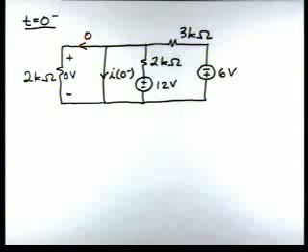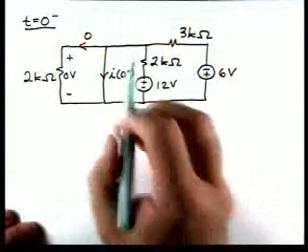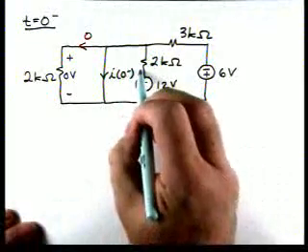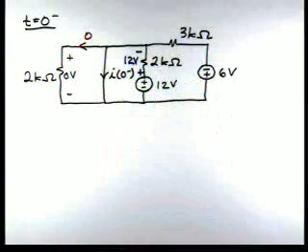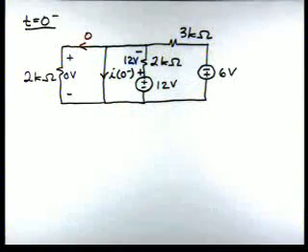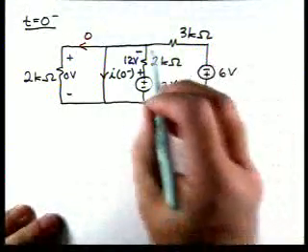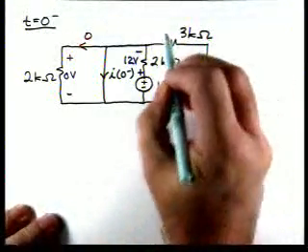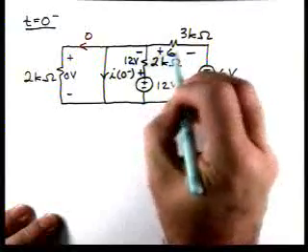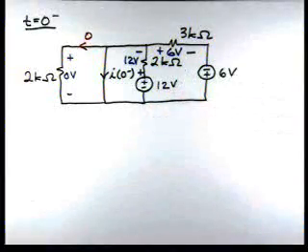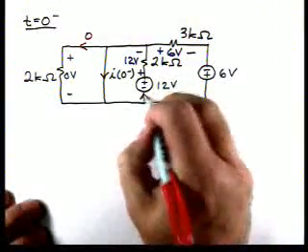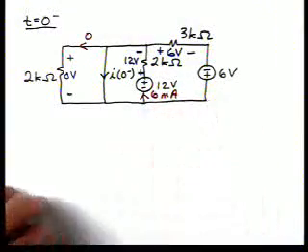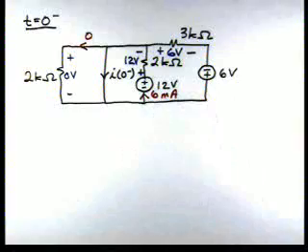And if we look at other elements in the circuit, for instance, if I apply KVL around this loop, that has to be 12 volts across that 2 kilo ohm resistor. And also, applying KVL around this loop means that there's 6 volts across that resistor. Now, as a result, that says there's 6 milliamps of current in that direction.